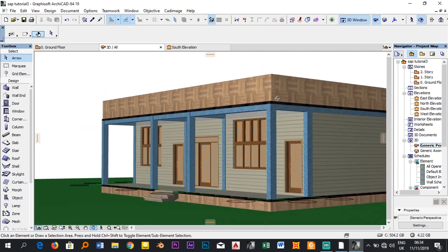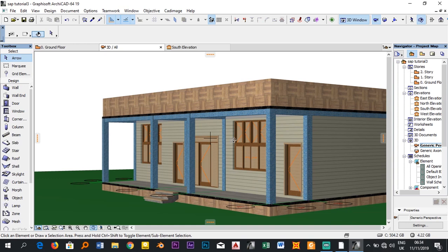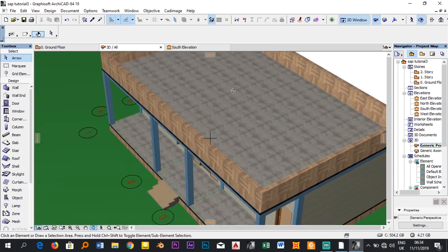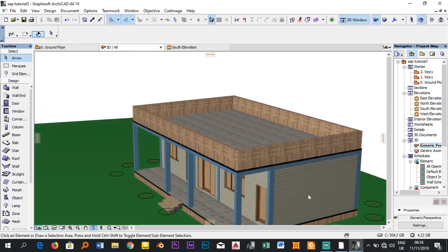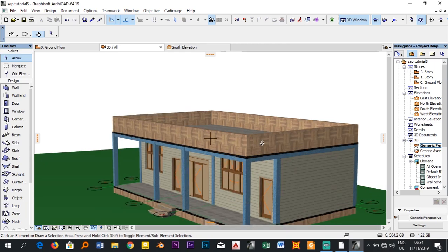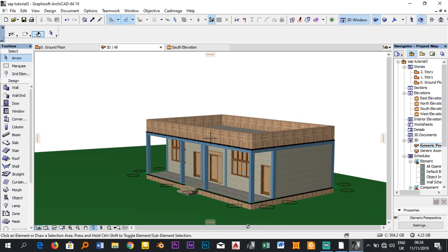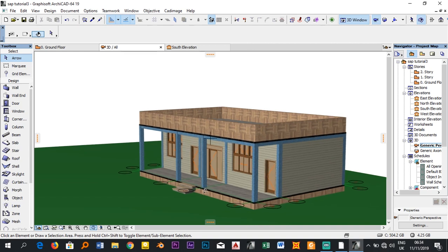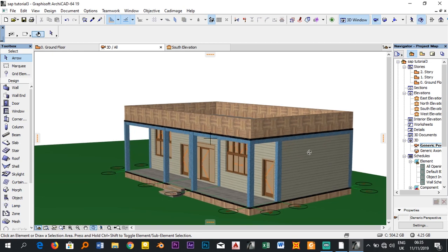This building has got columns and beams, and we have a solid slab on the roof. You have these kinds of walls around the building, and there is a parapet wall on the top tie beam of this element. This building also has foundations, isolated footings, so isolated columns will be provided below the grade beams. So we will see how to model each and every element here, however the walls will be modeled as a dead load on the beams.